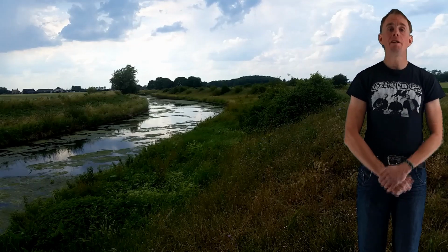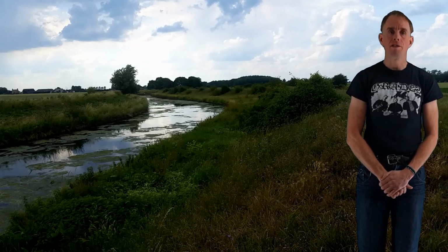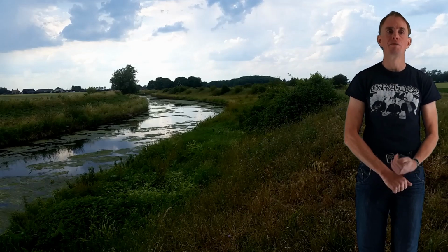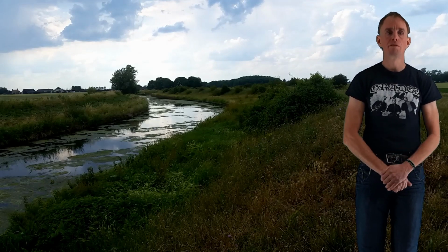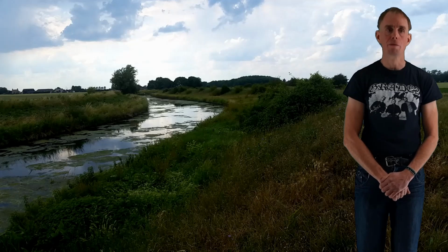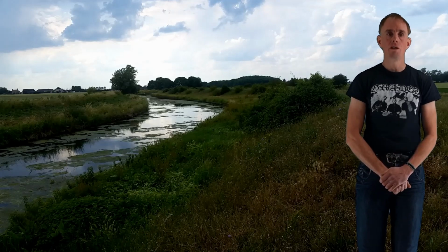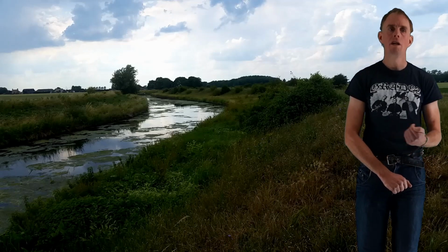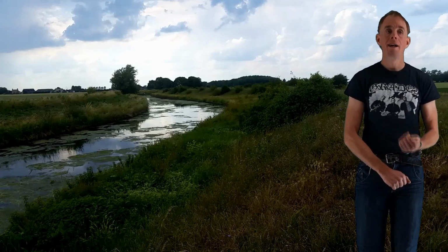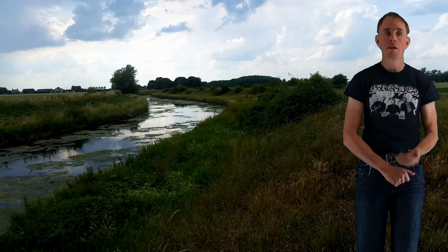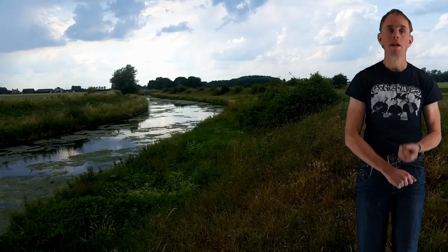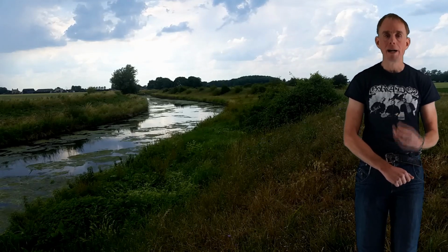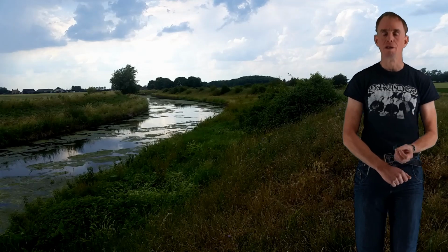In the previous part of Lesson 5, we used force balances to obtain the velocity profile and volumetric flow rate resulting from a fluid flowing in a cylindrical tube. From these solutions, we were able to construct a relationship between viscosity, geometry, flow rate and pressure drop. And this showed us how we can use capillary flows to measure viscosity so long as we know the fluid obeys the Newtonian constitutive equation.